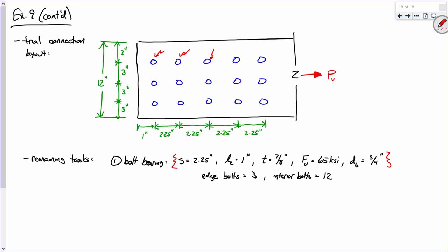When we were looking at tension members, we were saying, no, let's look at the entire member as one cohesive element. Do you see what I'm saying? And I'm saying that if you actually drill a hole, so here's your bolt right here. First off, when you drill a hole, you drill the hole a little larger, okay? But for tension members, we also said, well, this little bit of material right here around where we drilled has a bunch of burrs and maybe some damage due to sub-punching and whatnot, so we're not going to consider that effective for the whole member, okay? Does that kind of make sense? Is that a better answer?